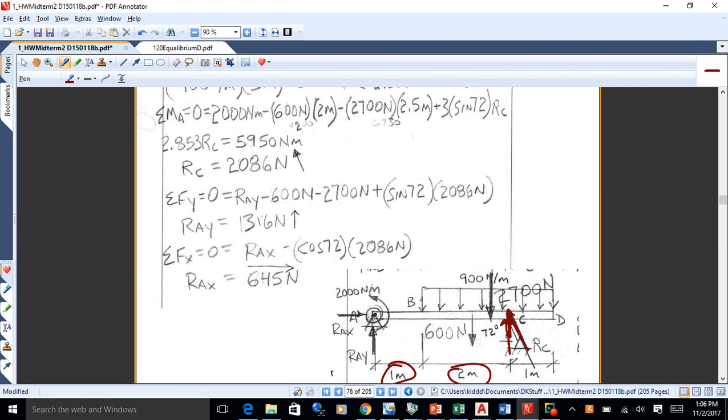And usually you start with a moment equation. That seems to be the norm, and figure out where that's going to be about, get 2 of the unknowns eliminated for the point you take the moments about, and then dimension from there to all the other forces, okay? And then you can come up with a moment equation. Okay? And then very likely you'll do 2 force equations after that because they're easier, okay? All right. Now there's exceptions, of course, but that's the general approach on these things.